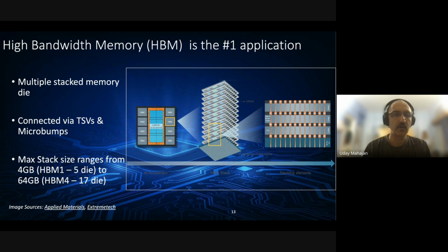This is because the memory is the bottleneck right now in AI compute. And these HBMs, through their high-speed data transfer between themselves and the GPU, enable much faster processing speed and, of course, manageable power consumption. And they are also able to manage the large current spikes that are generated during AI operations and other high performance workloads. And they're able to handle fluctuating load as well. So when an AI model is running, the power that it consumes is cyclical. It goes up and down as it runs and then stops between runs. So those kinds of transients can also be much better handled by this kind of architecture.